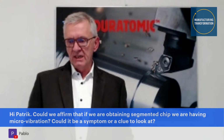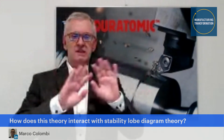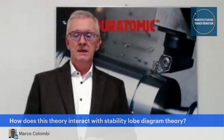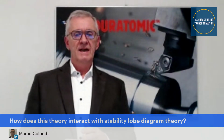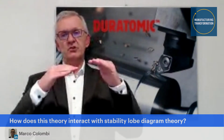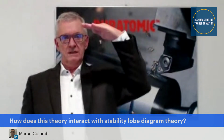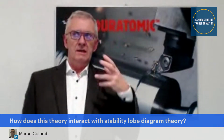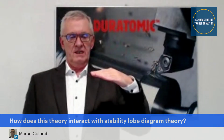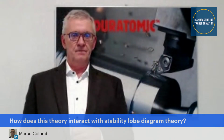How does this theory interact with stability lobe diagram theory? Nothing. That's a completely different thing. That is the same thing as the question with the machine tool resonance. You have to see it like this. A cutting edge moves. It has a movement vector. And normally, in theory, we suppose that that vector is constant in size and direction.